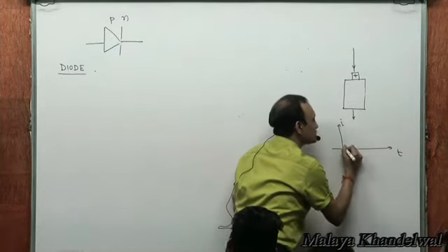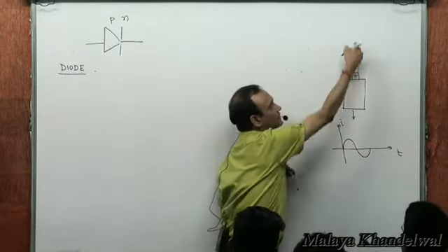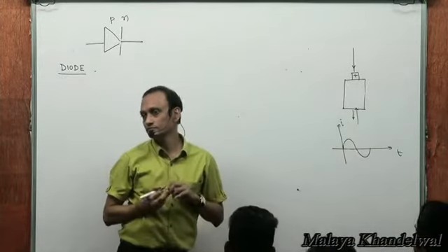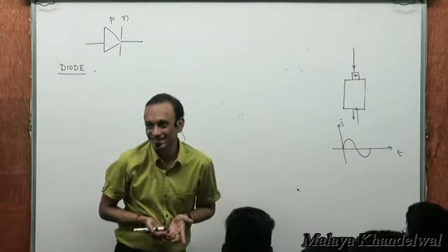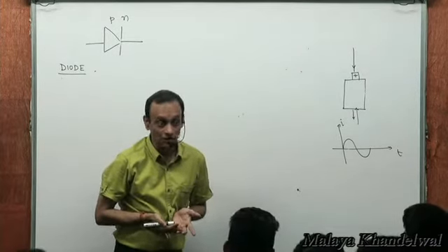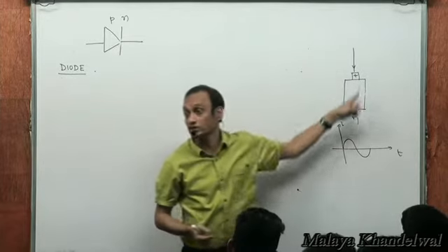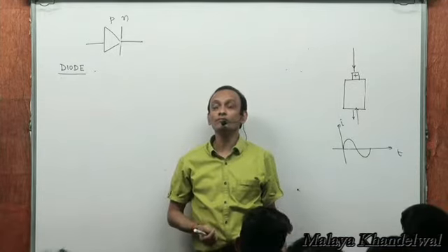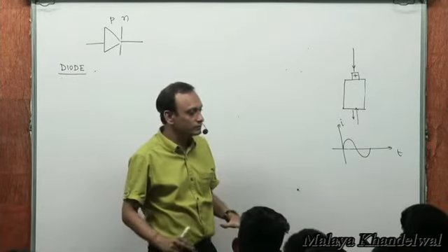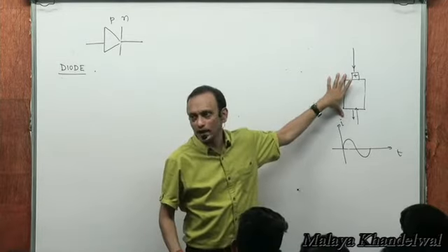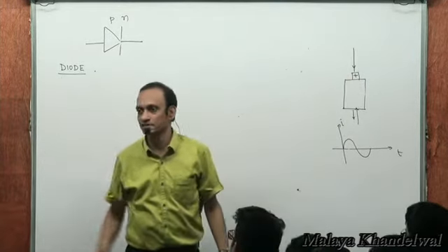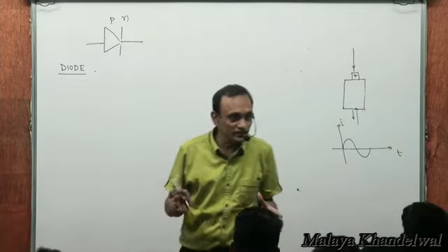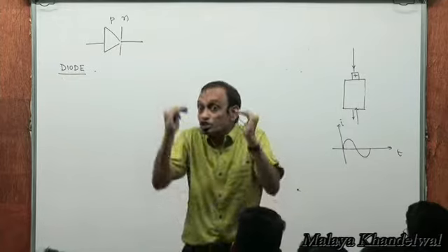So I versus T is going to be like this. In one half of the cycle, current would flow like this. In the other half of the cycle, the current will flow like this. Isn't it? Will it get charged? It will not get charged. Right? What you need is a unidirectional current. This is what you need. Not only that, the voltage that you apply to this is 230 volts. You don't want to apply 230 volts to your battery. That's very high. You want to step down that voltage.